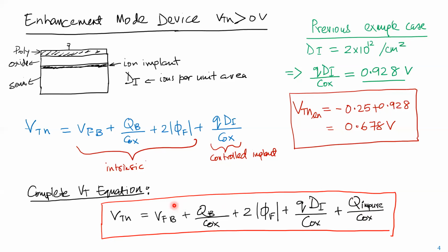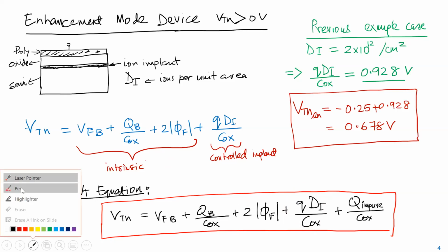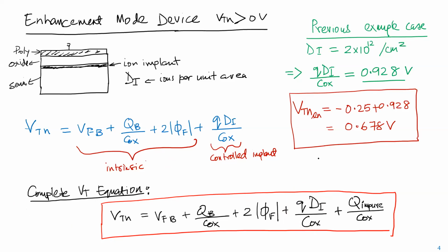So the big quantities are the flat band voltage, the Fermi potential you have to come over, and the implant you add to basically engineer the VT. For example, I think Puneet has been mentioning standard cells which are high VT, low VT, and medium VT and so on. So high VT would be, in a 0.18 process, maybe close to 1 volt. Low VT might be 0.2 volts, or this might be 0.6 volts, something like that.